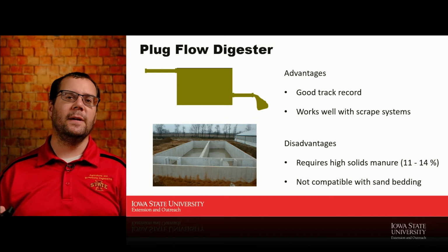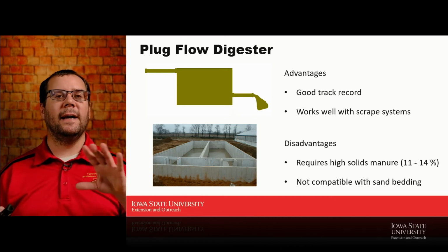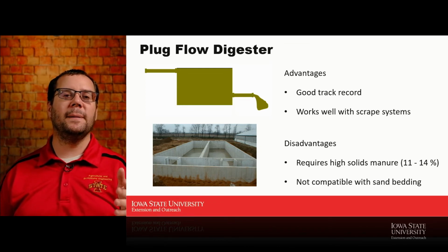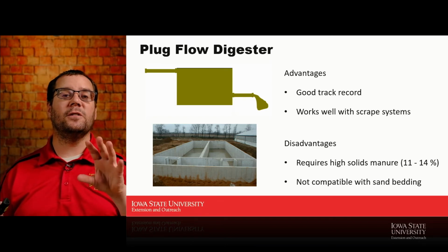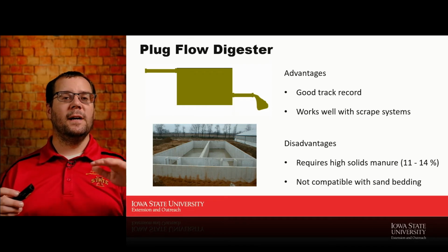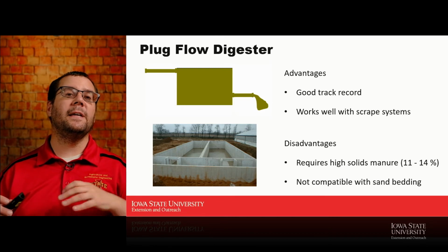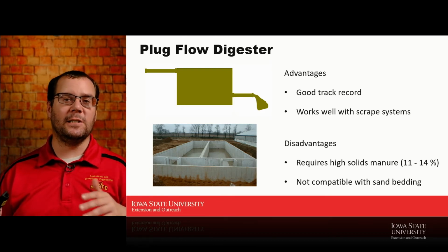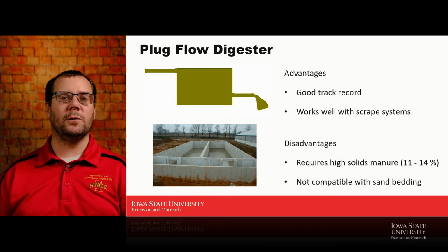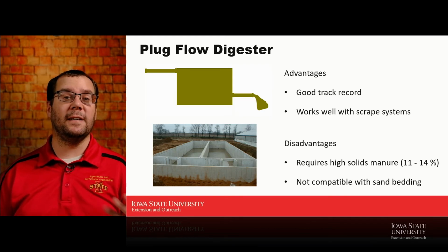Because of that, they really aren't compatible with sand bedding unless we're doing sand recovery before it goes into the digester. In the bottom picture there, I have a plug flow digester you can look at where it hasn't gone into use yet, right? The cover's not on top of it, so we can see what it looks like. What happens on that digester is on the end that's far away from us, on one side there's an inlet, the material will flow down towards us, have to turn the corner, and then it will flow back the other U and will pump out, right? So rather than making one long plug flow digester, it's U-shaped in this case. It's still a plug flow digester, even though it's a little different than how we conceptually drew it up. And we'll oftentimes do that just because it helps us minimize heat loss in some cases.